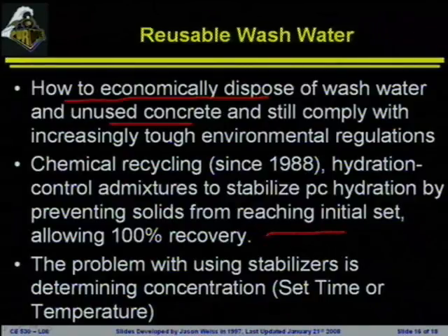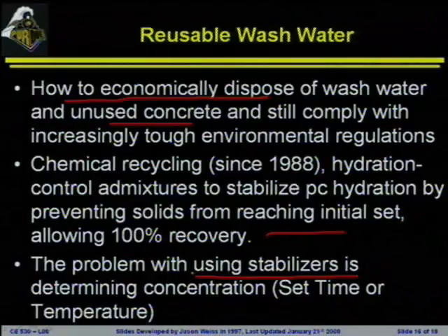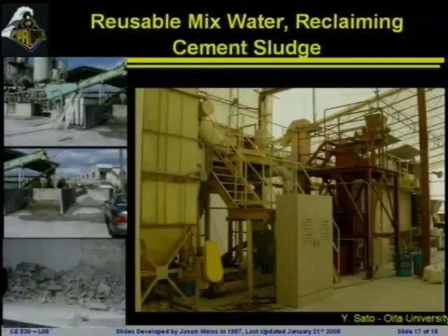Mainly here they're looking at the recycling problem. As I mentioned, there's a lot of ways that they will maybe put the material to sleep. Typically these will be referred to as stabilizers, where they'll drop an admixture in, it'll stabilize the system, and then they'll add another admixture the next morning that'll wake the whole system back up again and make it so it'll go back into reaction. Here is something that I had the opportunity when I was in Japan to see.